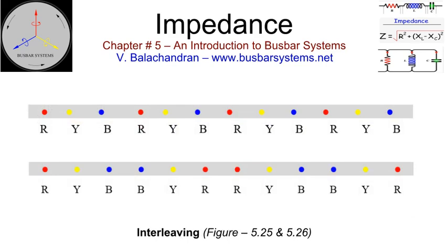Interleaving. In this arrangement, phase conductors are split in 2 or more parallel paths and interleaved. Interleaving of the conductors not only significantly reduces the shape factor, resulting in a low resistance, consequently increasing the ampacity, but also results in low reactance. These are effective only when the flat bus bars are located close, in a parallel plane with respect to each other. Interleaving is adopted in AC low-voltage high-current open busbar connections such as arc and induction furnaces to reduce losses